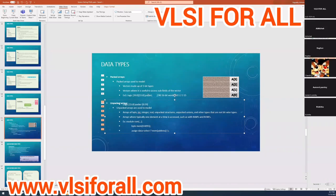So if you access the packet variable here, you are actually accessing all of these bits, which is 16 by 40, like 640 bits. But if you access packet 0 here, you are accessing only 16 bits, and you cannot access all of them at a time. You have to access only one at a time.